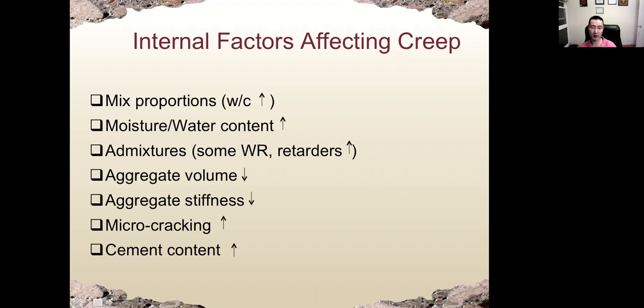More microcracks in concrete will increase creep, will also increase drying shrinkage. Increased amount of cement will increase creep and also drying shrinkage. Again, creep and shrinkage are a paste phenomenon. Only cement paste will shrink and creep. Okay.